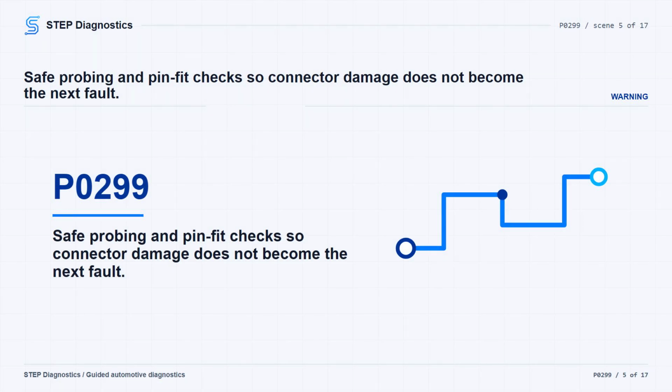When you connect test equipment or jumper wires to pins, use Rotunda Flex probes, NUD 105R025F, or Terminal Probe Kit 418S035, so you do not damage terminals. Check male to female pin fit for a consistent, strong connection. Use the mating pin to feel normal separation force. A damaged pin will have very low separation force.